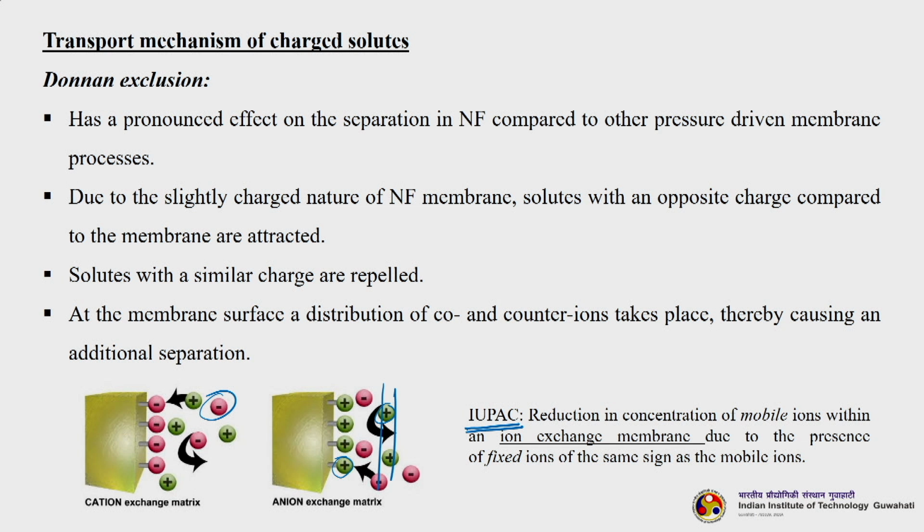Due to the slightly charged nature of the nanofiltration membrane, solutes with a charge opposite to the membrane are attracted. Solutes with a similar charge are repelled. At the membrane surface, a distribution of co- and counter-ions takes place, thereby causing an additional separation.